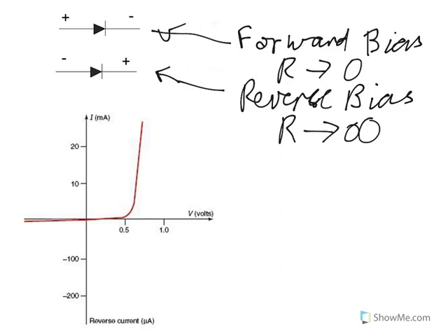Again, with diodes you would have a data sheet showing the voltage-current characteristic, and here's one below. You see that when we're trying to get current flowing in the reverse direction, we really don't get anything much at all, so very high resistance. But in the forward direction, it takes a little bit, there's a little bit of resistance, but then eventually it takes off.